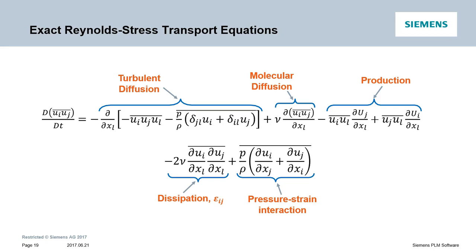Okay, great. We have the Reynolds stresses. Now we can feed this information back to our RANS equations and close the system. And our work here is basically done. Not really. The reason being, this is not a closed system of equations for the second moment or Reynolds stresses. While the molecular diffusion term and rate of production are known terms, the remaining three terms are unknown.